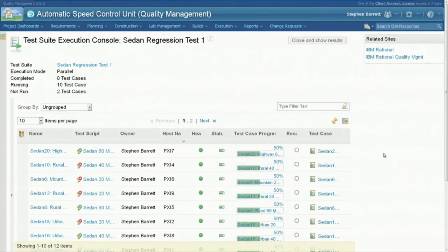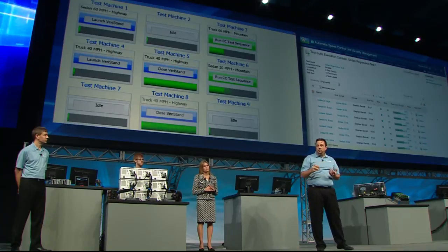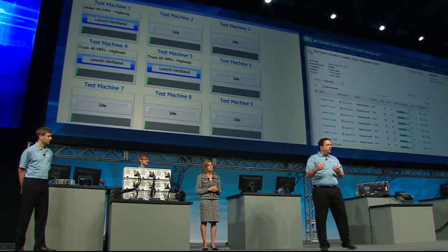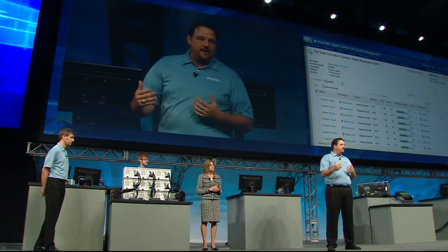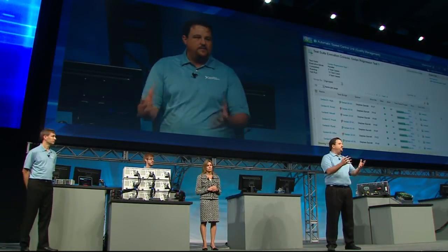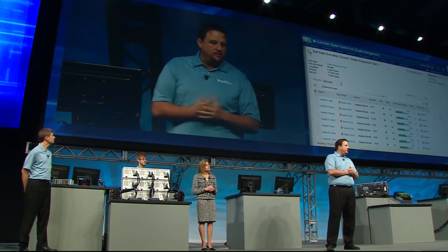They begin running by downloading the latest version of the embedded software to the unit under test. It then will deploy a series of NI VeriStand hardware-in-the-loop test scripts to exercise the unit and acquire data. And finally, it will use DIAdem to automatically analyze those results and produce those engineering reports, and then place all of this information back up into the Rational Quality Manager system for defect management and traceability. Right, so I think it's pretty cool too.